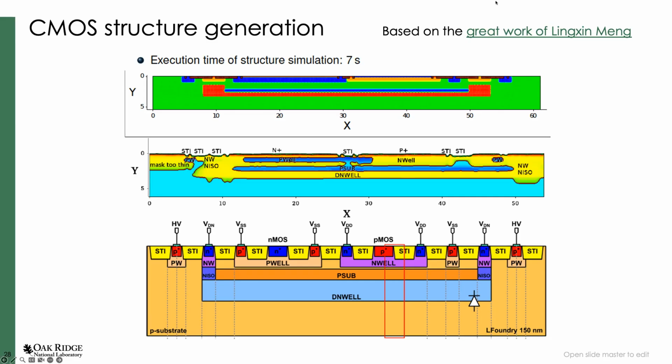And when we did this device here, we would define what's happening here and everywhere from that text file. And we compare, so I did put the slide there, I could maybe put it next time. When you compare both, it was matching quite well at the end for what we were looking at, which was where the breakdown is, what's the depletion as a function of depth, and as a function of bias voltage. That was working quite well.